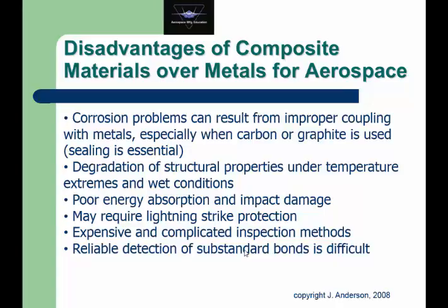It happens some with thermosets, but it's more pronounced with thermoplastics. When you get high temperatures and a lot of water available, you get oxidation of the plastic material. So you get a breakdown of the polymer chains, and you change properties. It tends to make polymer materials brittle and form cracks.